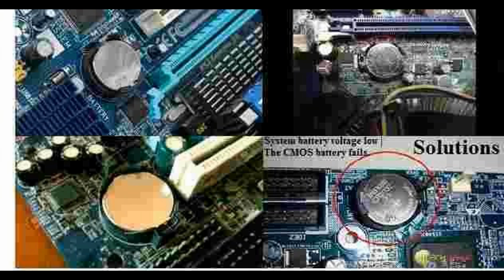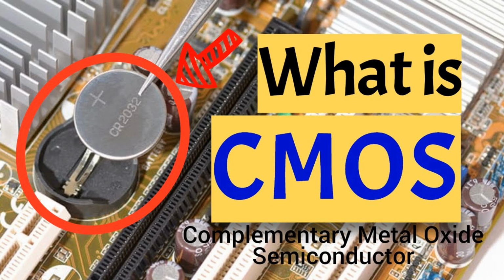Input and output logic levels. When the input to an NMOS transistor is high, logic 1, it conducts, providing a low resistance path to ground. This pulls the output voltage down to near ground potential. Conversely, when the input to a PMOS transistor is low, logic 0, it conducts, providing a low resistance path to the supply voltage. This pulls the output voltage up to near the supply voltage level.